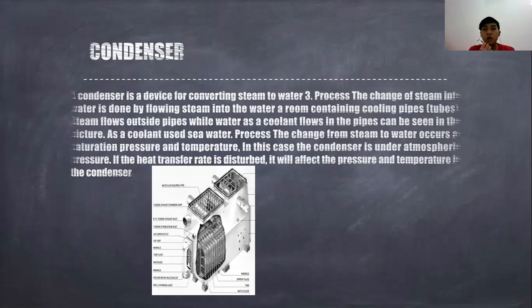The process of changing from steam to water occurs at saturation pressure and temperature. The condenser is under atmospheric pressure. If the heat transfer rate is disturbed, it will affect the pressure and temperature in the condenser.